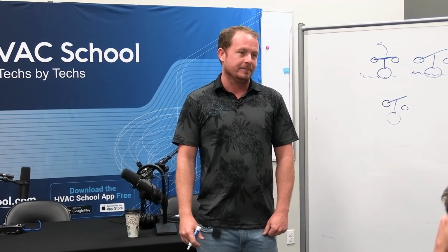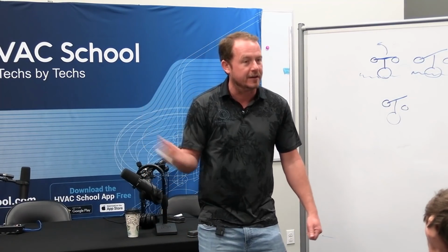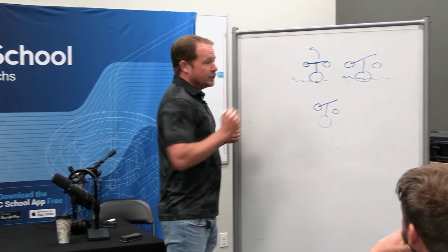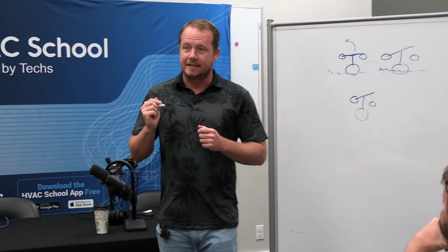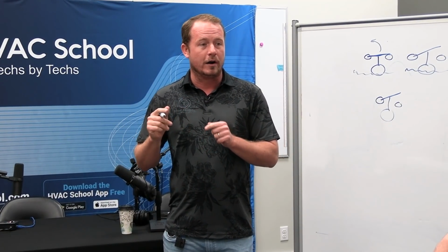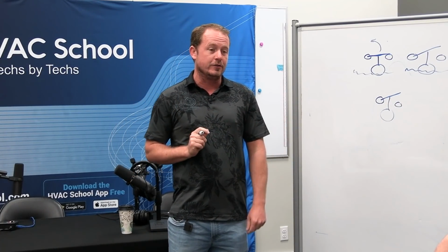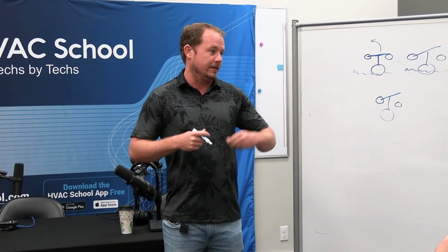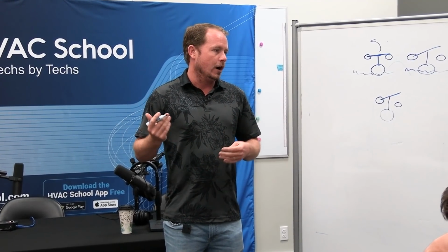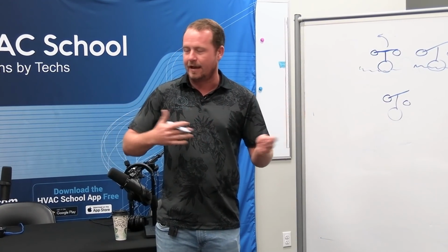Not likely. It's more likely that you have teenagers in your house and they keep slamming the door all the time and then it falls off its hinges. That's much more likely. If a float switch fails open, it's likely that it's been going open and closed a lot. And if there's no water in it now, it's likely that there was water in it before. So if it's stuck open and it's broken, you have to replace it, but try to figure out why. Odds are that it's been overflowing and consistently having an issue.